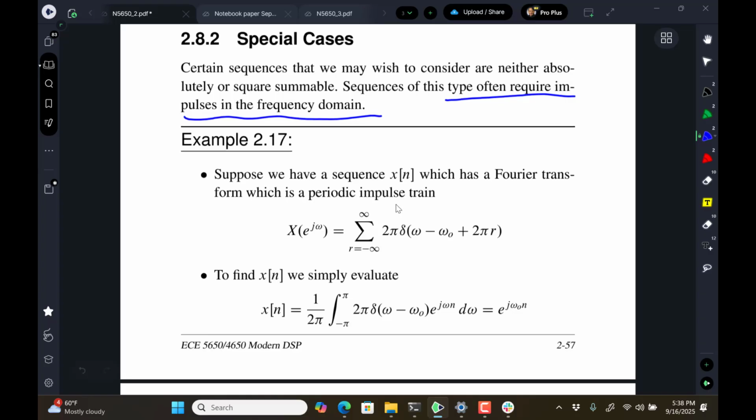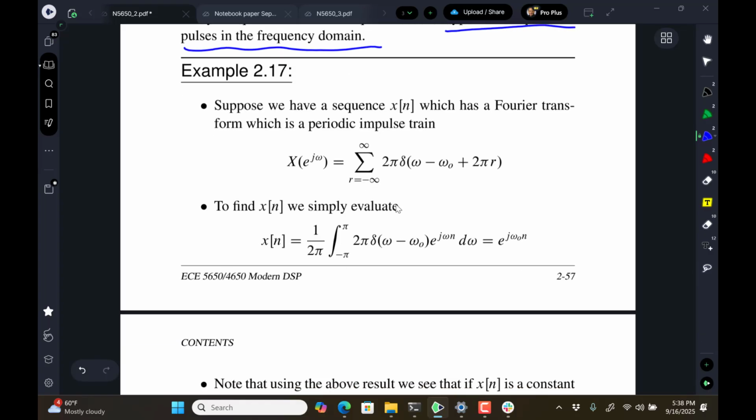So in the discrete time domain, we carry that forward, and we have an impulse train. Why do we have to have an impulse train? It's because if it's going to be a valid spectrum, it has to be periodic. Remember I mentioned that a while back tonight. Any spectrum in the discrete time domain is always periodic with period 2 pi.